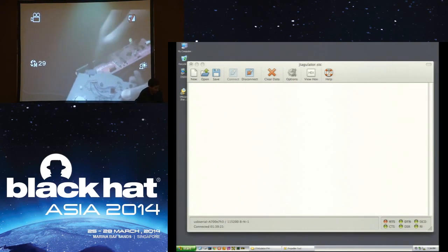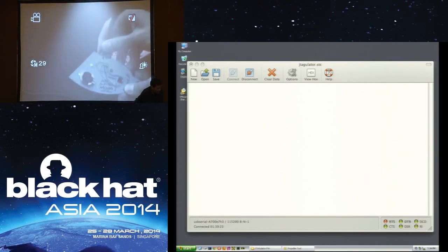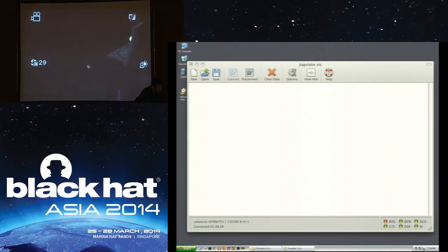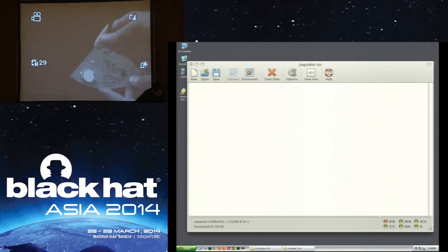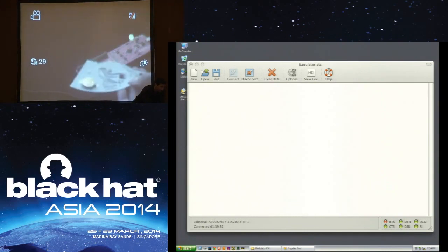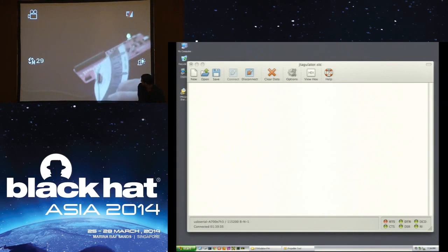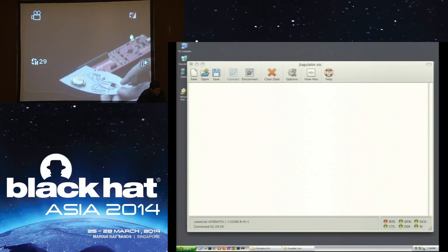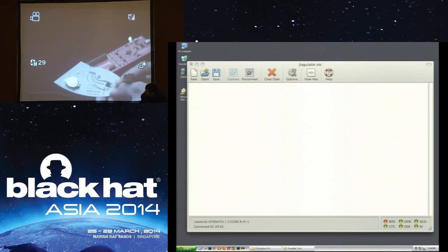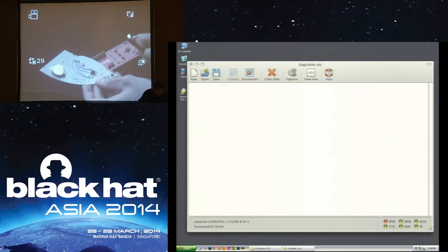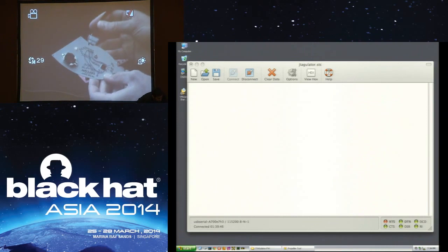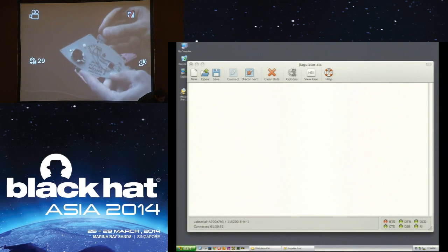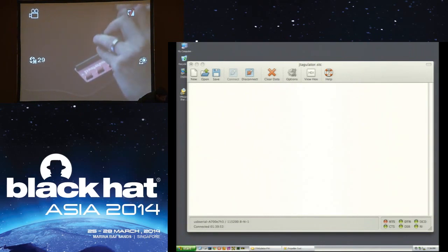So I have a little 5-pin header here, and then I have a cable connected to this DEF CON badge, which is an MC56F8006 digital signal controller that has JTAG. I designed this DEF CON badge a few years ago. This was DEF CON 17, and it just happened to have a JTAG interface. I had brought out the JTAG pins to test points on the board. So for the demo, I made a little cable, wiring the test points to the cable, so everything is kind of hard-coded. So I'll give that demo first.